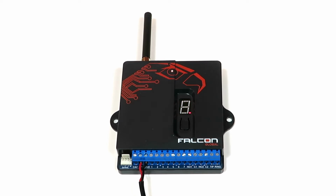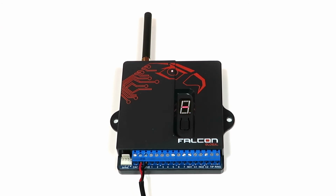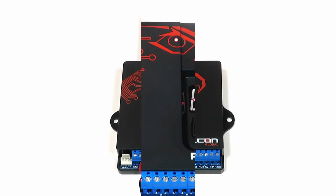Once it's connected to the GSM network, it will display the priority of the network it is connected to, as well as the signal strength of that connection. In this demo, it shows that we're connected to priority network 1 at a signal strength of 6. This is a signal strength out of 9, 1 being poor and 9 being excellent. For great app connectivity, we recommend a minimum signal strength of 5.